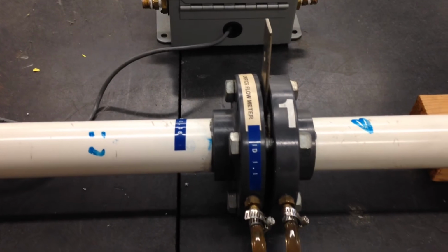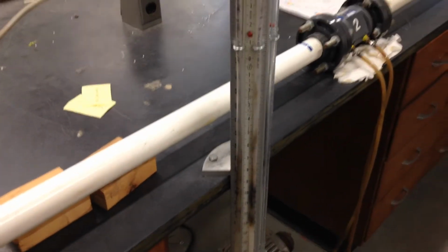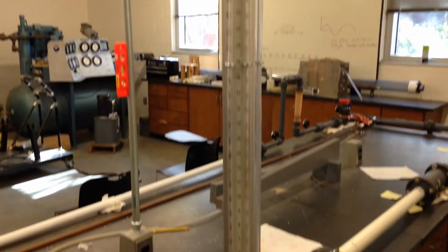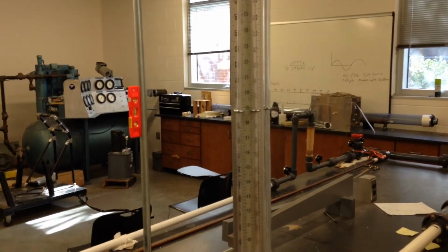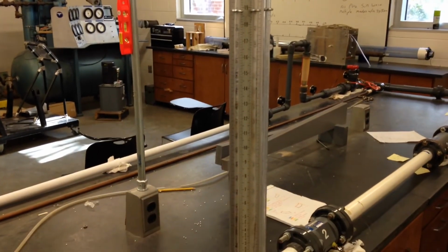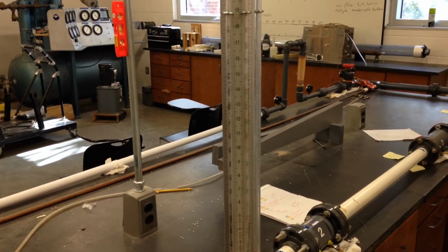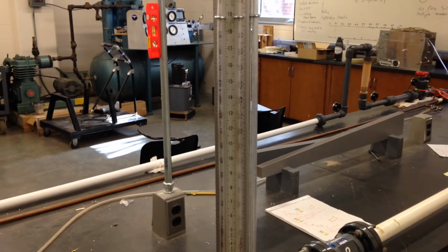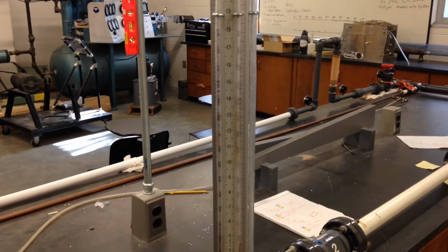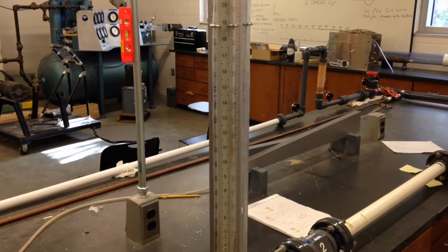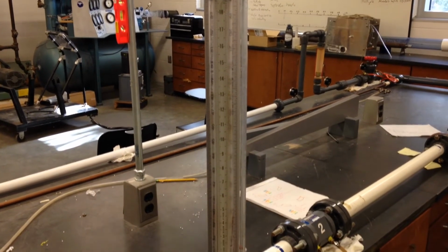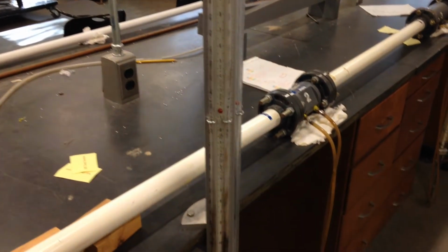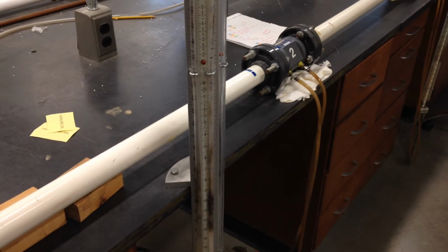And you can see it there with the ports to its manometer, which is a conventional fluid manometer, dual column height. When you take your data, you'll see a lot of data on this and the other manometers, and there are 2 things I want you to notice. First of all, the only important thing is not the absolute height of the water column in the manometer, but the relative height of the 2 columns.